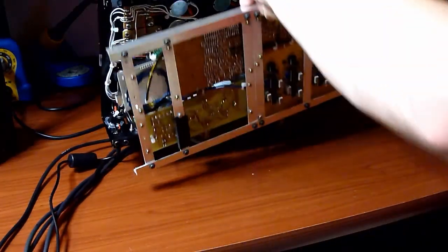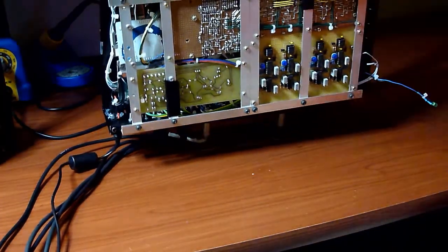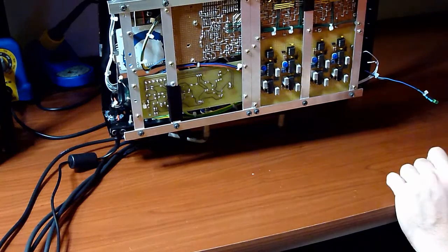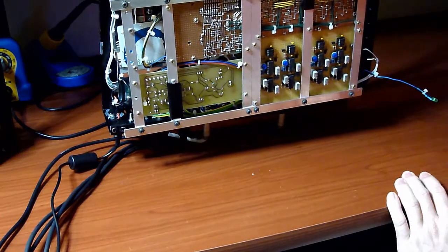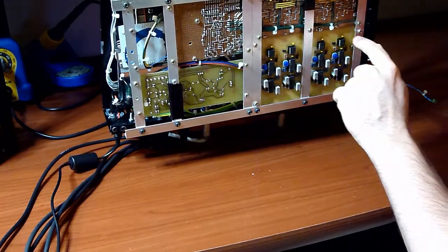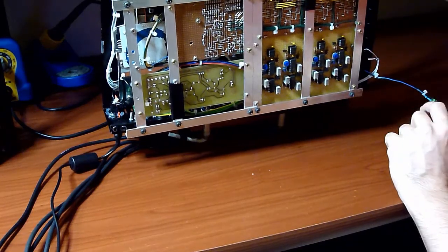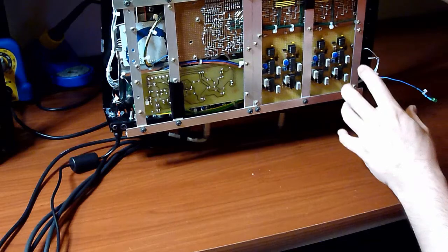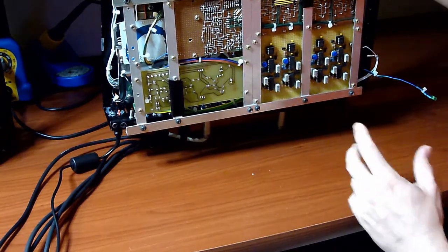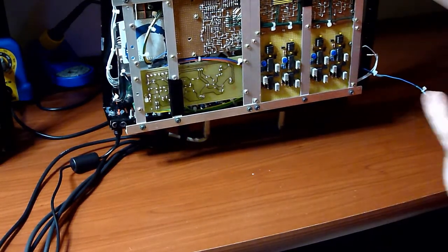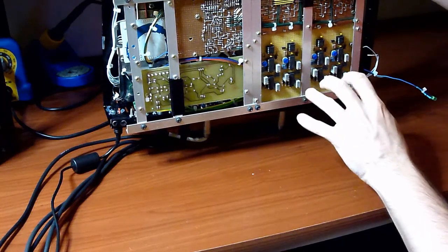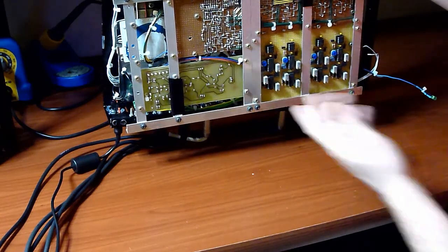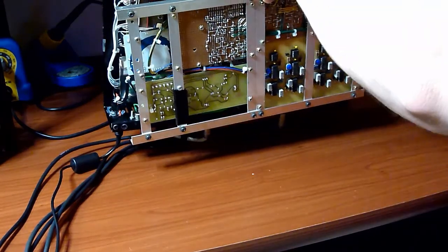And now if we look completely under, we can see in this area here the digital to analog conversion. We have the digital to analog converters at the top here, those chips, and then we have op-amps here to scale and bias the output to have a really precise output when we directly connect to the synthesizer.